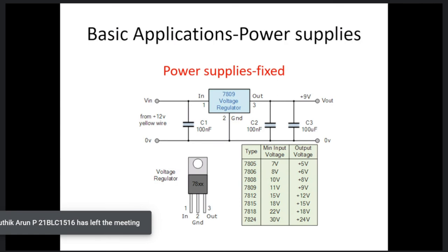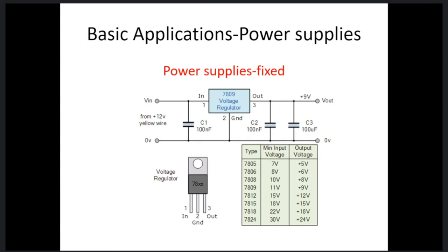Even if you see an industry, you have a lot of machineries, a lot of sensors. There is a big difference between the textbook and the practical industry. In practical machinery, it could be a machine that works with pneumatic or hydraulic, which is not electronics. There won't be any electronic components, but the module that activates the pneumatic or the hydraulic, that is the electronics, that is the application area. When it has to free the jig fixture, when it has to hold the fixture, these are the applications.